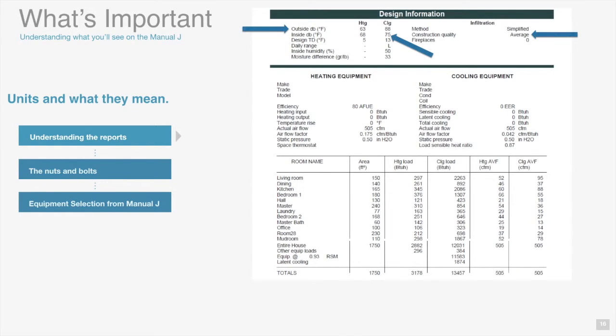And then construction quality. The typical house being built to, let's say, for instance, the 2009 code that's adopted in most places now, if not beyond that, is a pretty good house. Construction quality here refers to the air tightness of the building: 7 ACH50, 5 ACH50 here in Austin. That's not all that bad.